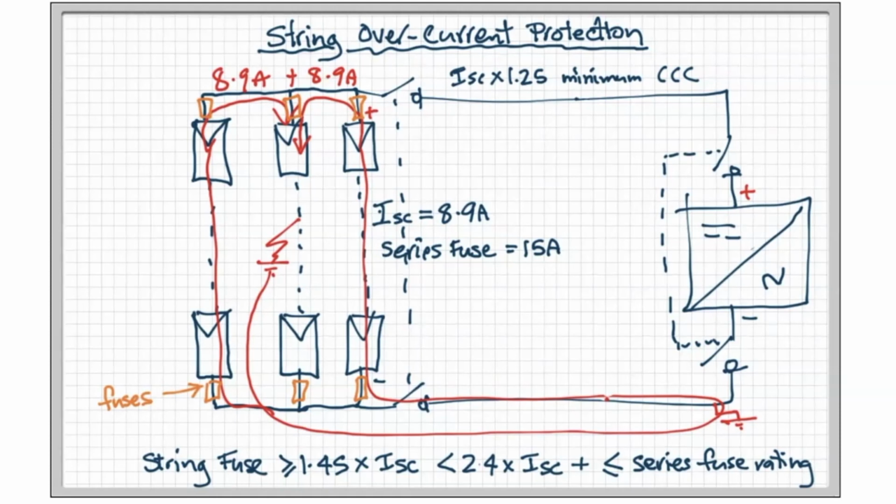This one goes back a few slides, I think, and sorry if you've answered it, Glenn, but someone just asked about the 15-second monitoring resolution for surges. Is that 15 seconds a bit too long? Because surges occur quicker than that. Well, in a way, I'll come to this when I show you a data sheet for an inverter and how they rate that surge demand. It does depend on the appliance, the inverter, what its instantaneous peaks are. So let me answer that by talking about a particular inverter and looking at its data sheet.